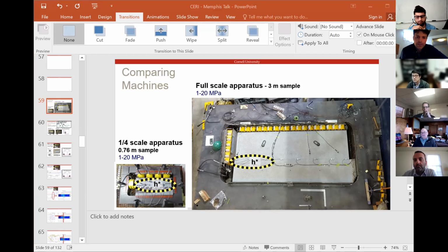Yeah, so what happens is we can control it a little bit. I originally thought we'd be able to just put more pressure on some of these cylinders and less pressure on the others, and basically define our stress distribution. But when I tried that on a smaller scale rig, I realized that's a good recipe for just cracking the rock in half due to bending.